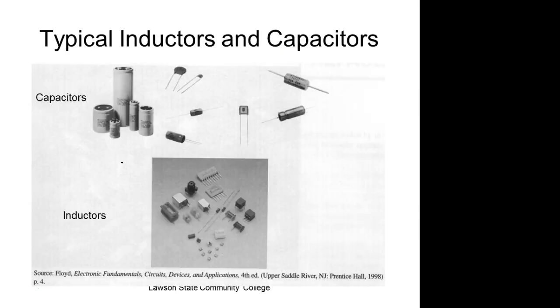But we get a phase shift, right? You understand that? So thank God for phase shifts, because if we didn't have phase shifts, there would be no such thing as a single phase motor. Before a motor can turn, all your electrical motors work off the repulsion and attraction of magnetic fields. And one of the fields has got to do what? One of the fields has got to move. Three-phase, we have no problem because the fields are causing it to move. Single-phase, though, if you didn't create a phase shift, that thing would just sit there and hum at you.